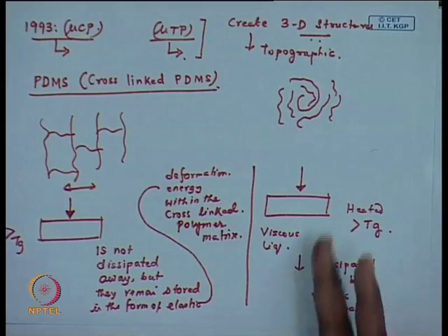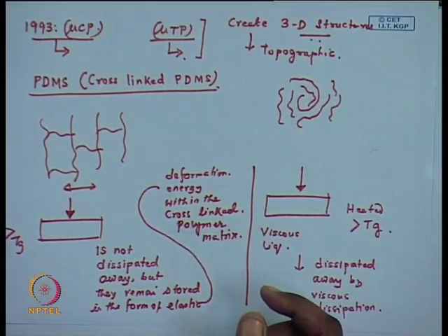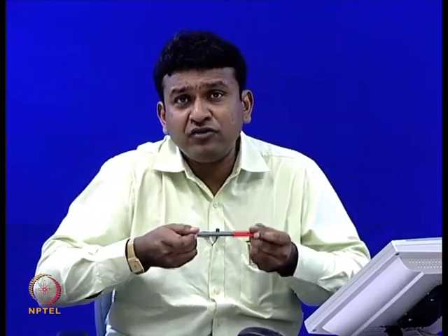So, once that externally applied force is withdrawn, there is no energy available to restore the deformation on the film surface. In contrast, this is what gives the flexible property. So, you stretch an elastomer, you are applying deformation, which leads to stretching of the molecules, but the force you have applied is stored within the elastic matrix. It is not dissipated to the surroundings. So, the moment you withdraw the stretching load, those forces trigger the retraction of the entire block to its original configuration.